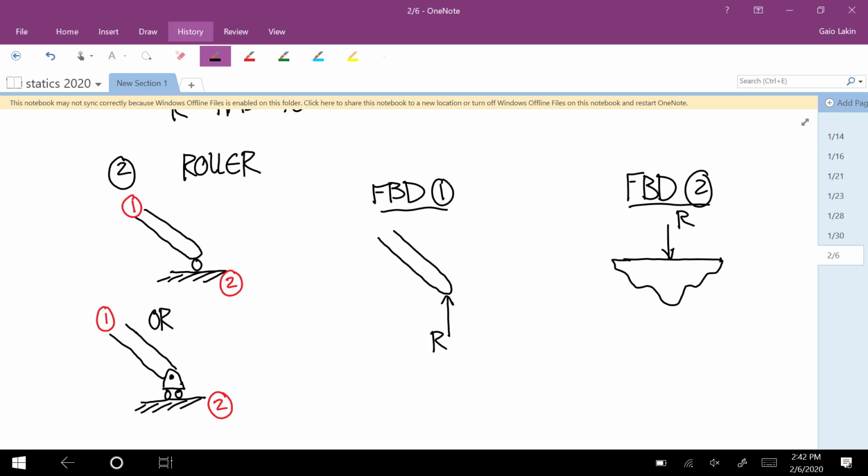And again, think about what degrees of freedom are removed by this joint. And when you're thinking about these joints removing degrees of freedom, imagine that the joint is connecting it to something rigid, to the ground or something. Okay, so don't think of this as another body that's able to move, even if it is. You have to think about it as if that's fixed. Now, what does the joint with that fixed body do to limit the motion of the one?